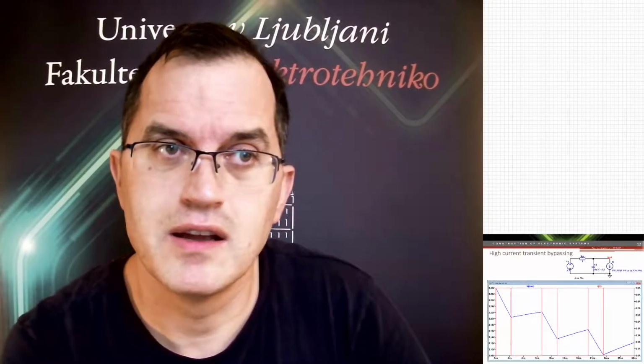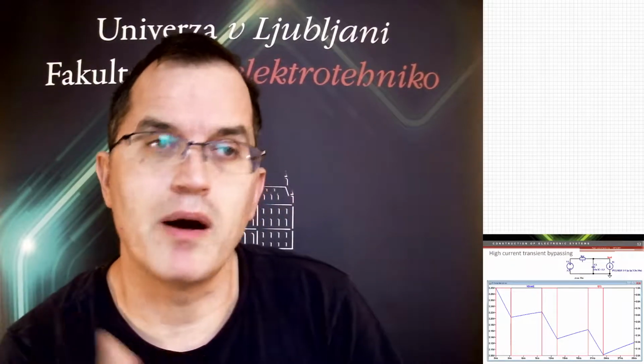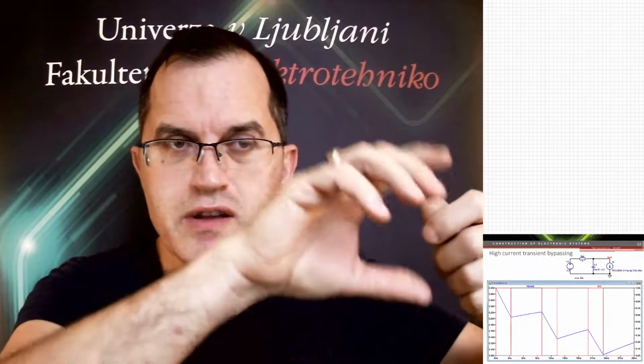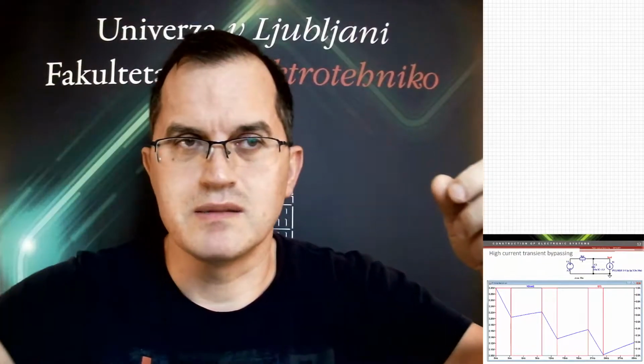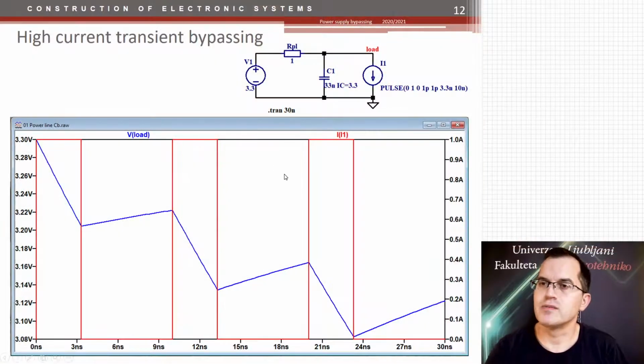We forgot to take into account that the capacitor is not just for one single current spike. These spikes repeat all the time, so they have a certain frequency. And that capacitor also is connected to a power supply network, to a power source, which is connected to this chip via some tracks on the PCB, and all that affects the operation of the power supply in general. So we have to apply the knowledge of our power supply circuit as well.